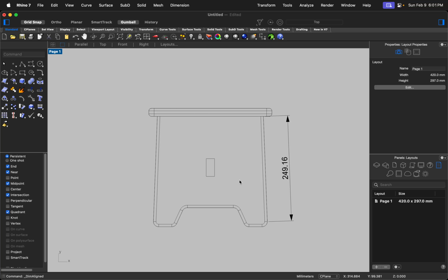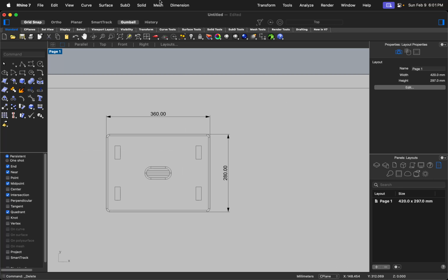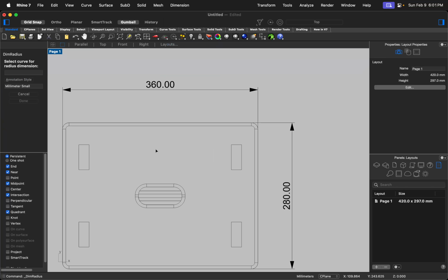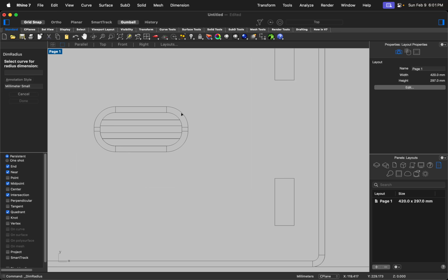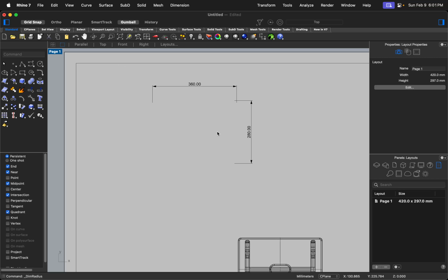Okay, an aligned dimension allows you to align the measurement wherever you want. It won't align perfectly vertically and horizontally. You will go with the angle that you are measuring. Last but not least, we're going to measure the radius or diameter. You can use radial or diameter if you want. You can just click here, the outer curve, which is approximately, oops, wait, hang on, something changed.